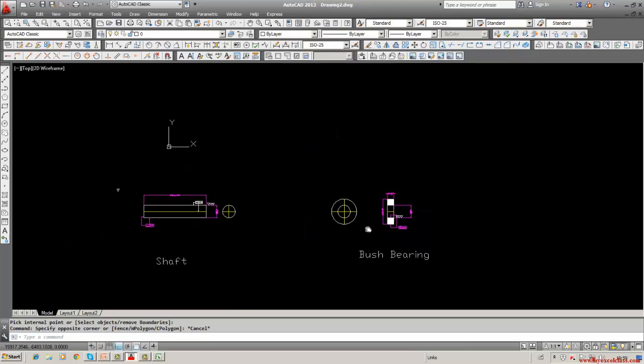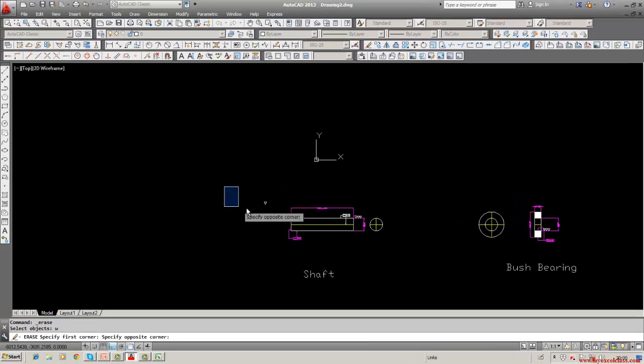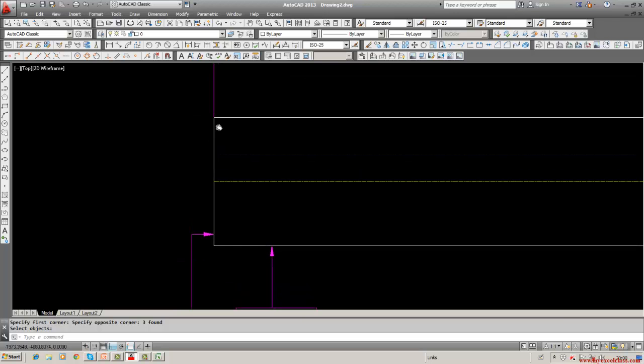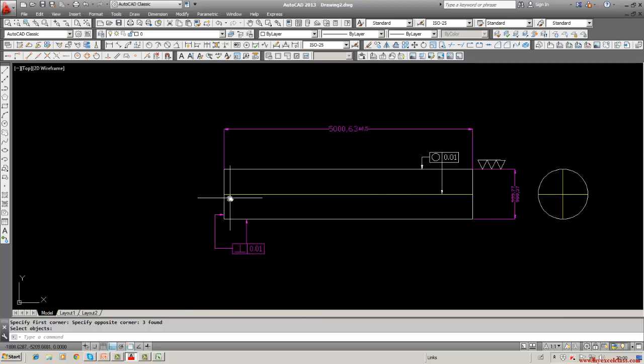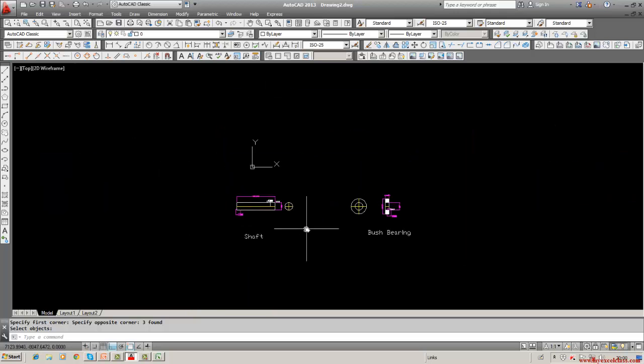So this is shafts. One more thing I have to mention here. The shaft will not be sharp. It will be chamfer. You know the chamfer command, you can always chamfer the shafts. I am not explaining here, I have already explained it earlier. So this is how tolerance can be made. Basically, you should know some basics of tolerance, limits and fits, and the knowledge of drawing, process drawing or whatever may be the type of drawing.